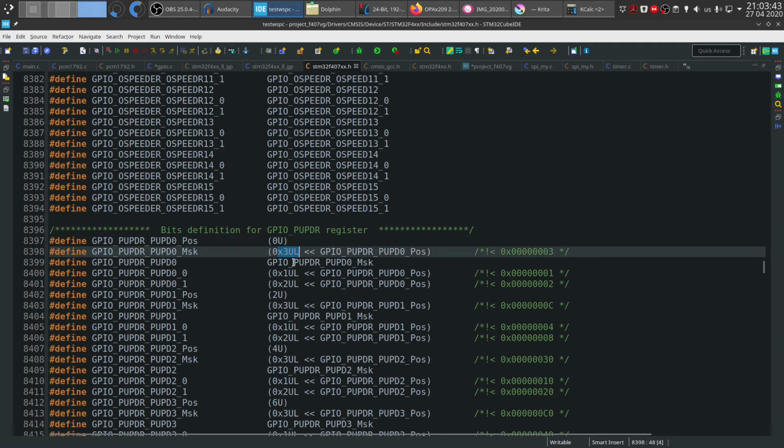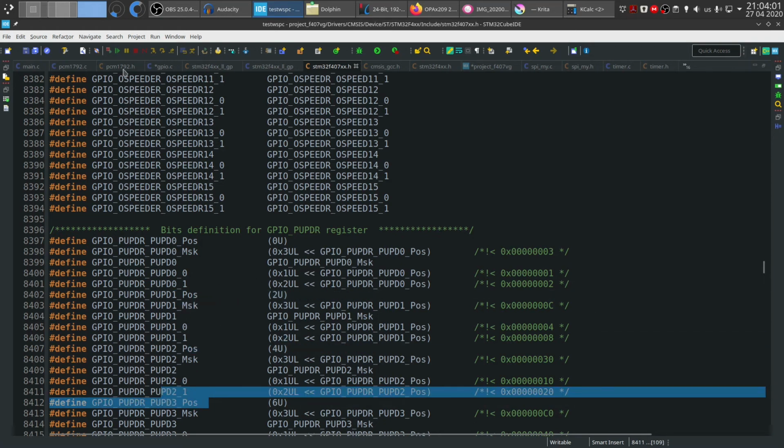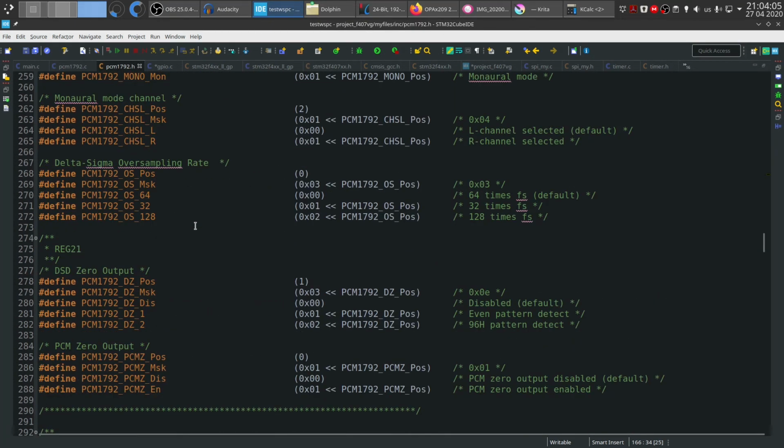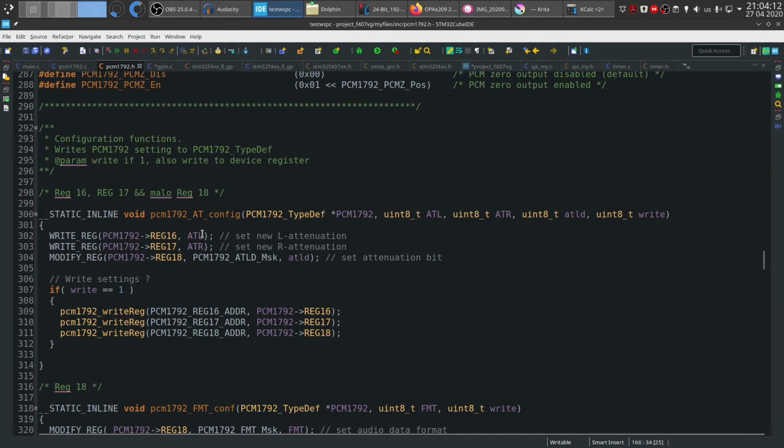Therefore, this configuration has 2 bits. And these are the different configurations for this one. So it's 1 left shifted by the position and 2 left shifted by the position. And again with the new setting. And again with the new setting over here. So this is how I approach the macros. Macros are pre-compiled, therefore they don't actually use any space on the processor because they're just copy and pasted by the compiler, and they're just dropped in place over here.